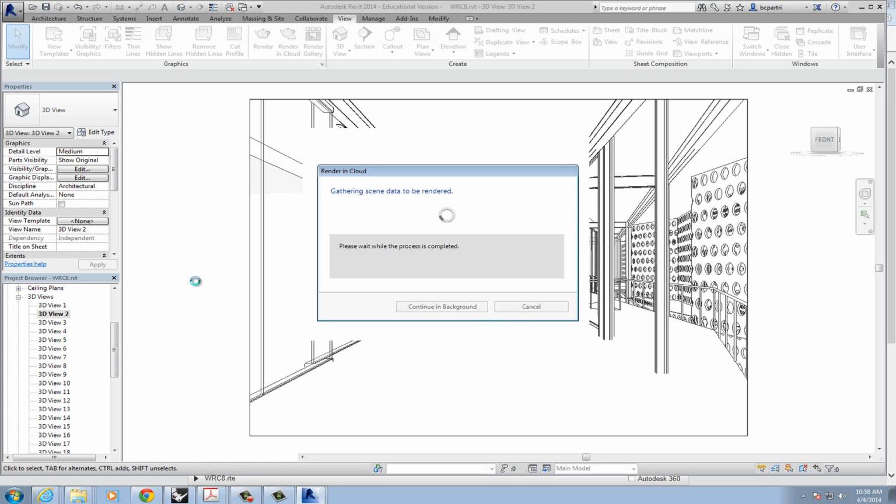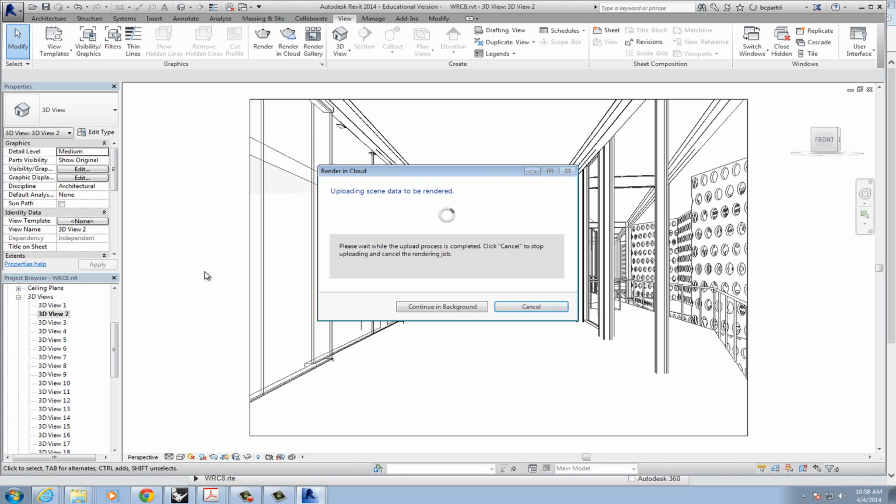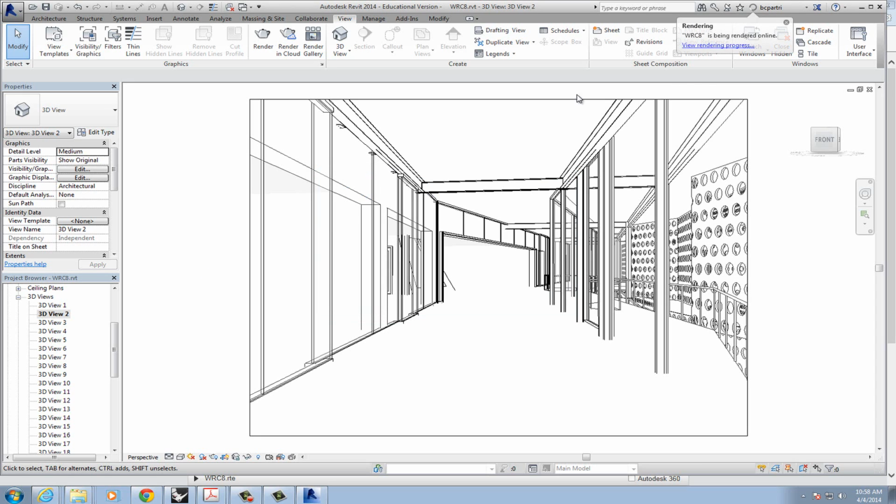Right. But what it is, it's a spherical panorama of the model. So you put yourself in the middle of a room, hit this, and then you can use that to visualize the entire room. I use this in my personal workflow to look at what I'm doing as I'm working. I might run those before I even know what my materials are, just to get a sense of what it feels like to be inside of that space.